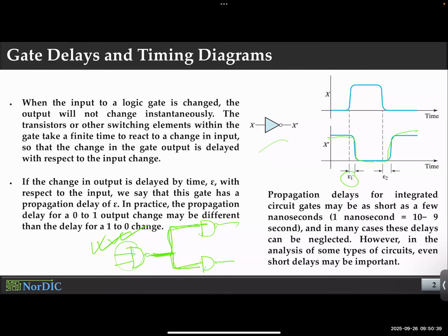2, exactly. It looks simple, like childish, of course, but these are extremely important metrics to keep in mind and to familiarize yourself with. The fan out of a circuit determines the delay, because we are talking about the timing diagrams here. So the delays are important. The more nodes or more gates you drive, the higher the delays. Let's try together. Okay, did I tell you that sharing is good?